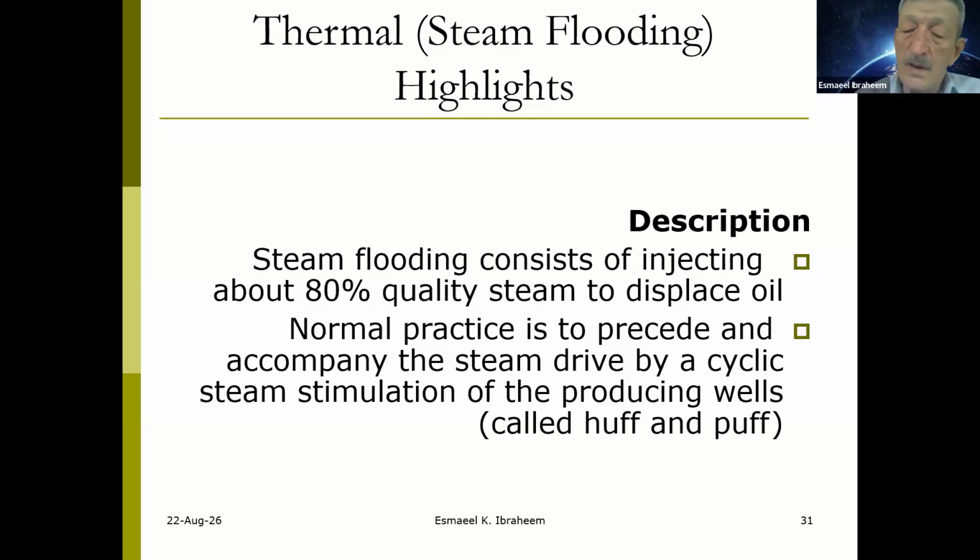called huff and puff. This is an operation that's called huff and puff. For some time you inject steam through the injection well and produce the oil and water from the producing well. At other times, I repeat, you reverse the operation, making the injection well a producer and the producing well an injector.